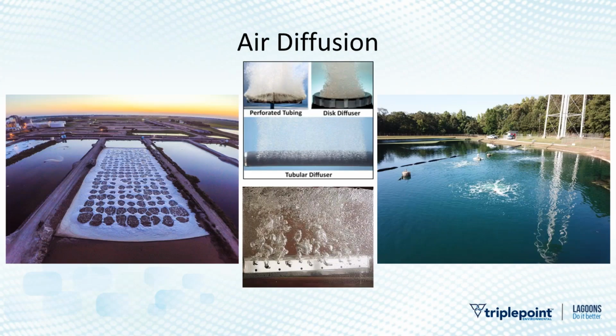The next methodology, this tends to have been blossoming a bit more in the past 20, 30 years, is air diffusion. Instead of throwing the water up into the air, we're going to pump the air down into the water and release it. And the principle behind this, the idea is pumping air is simply less energy intensive than pumping or moving water. So this tends to be lower from an energy cost standpoint. And you can see here, here's a side profile where the bubbles are released at the bottom and the bubbles just rise to the surface.